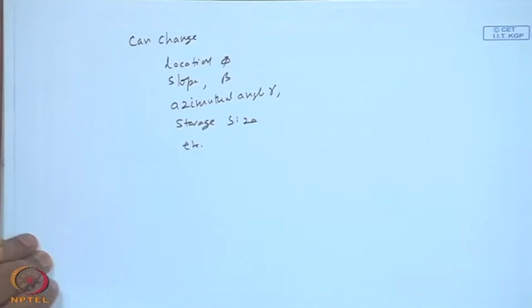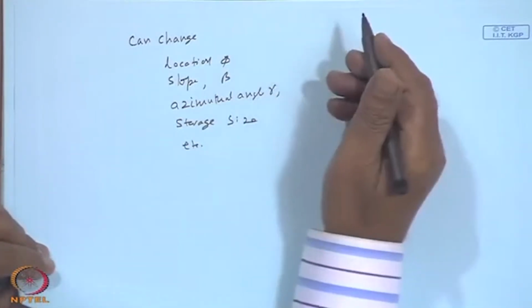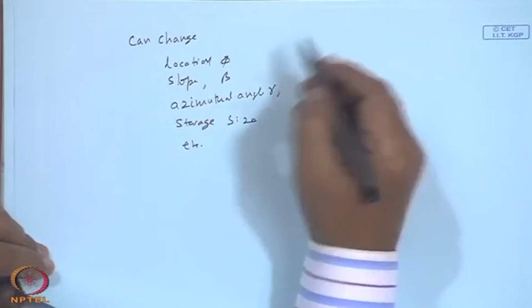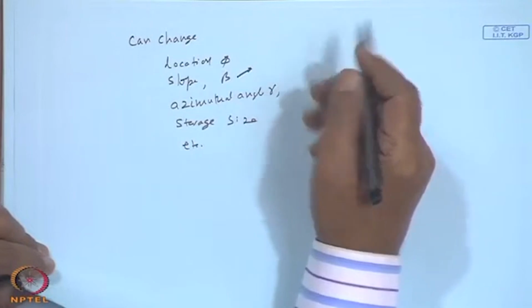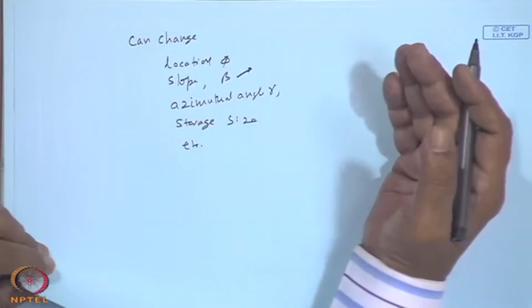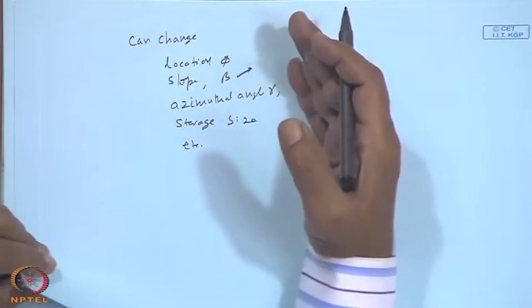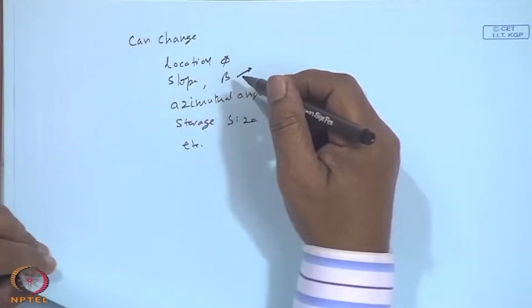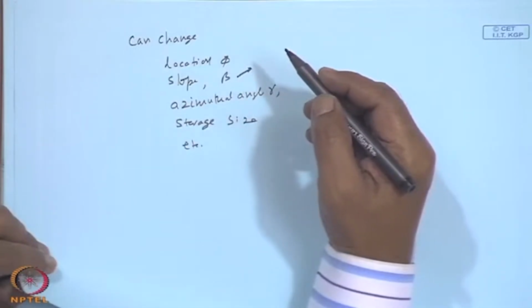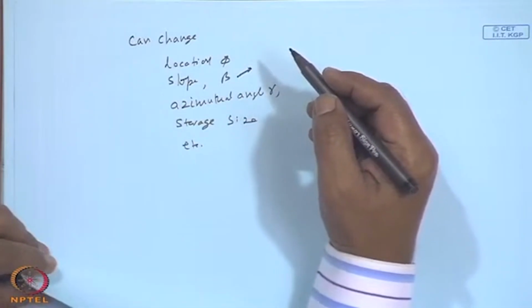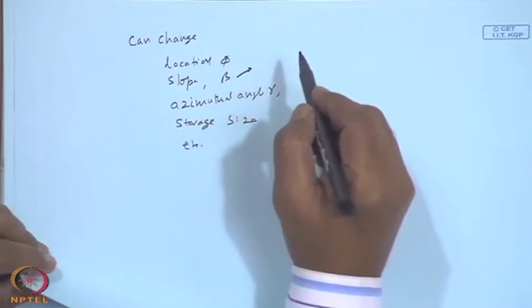once the complete linking of the simulation of the system model is complete, we can make a simulation for Chennai, we can make a simulation for Delhi, Srinagar, Simla, Darjeeling, whatever locations you want, and then find out the best beta for that particular location. Either you independently optimize or maximize the solar radiation falling, or we will be ultimately going through the solar energy system performance, because the excess radiation at times may not result in higher load fraction improvement if f is already equal to 1.